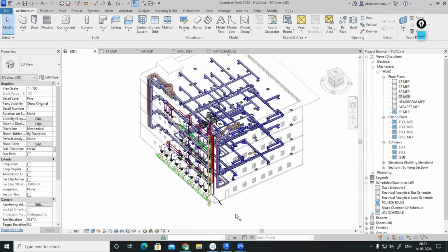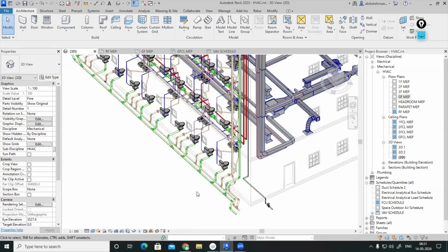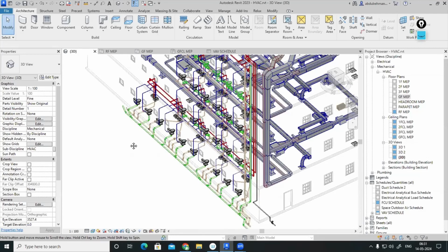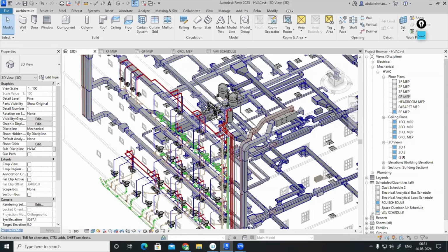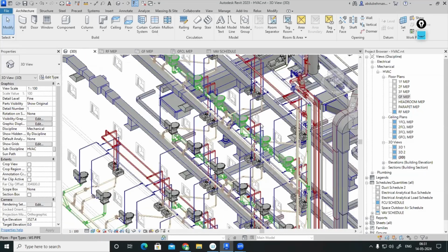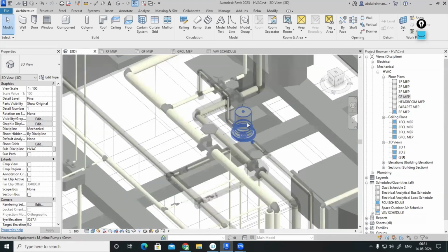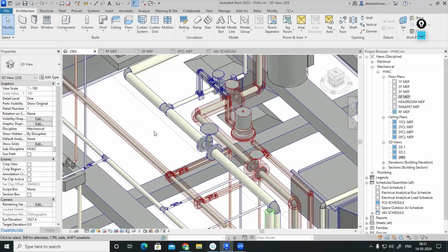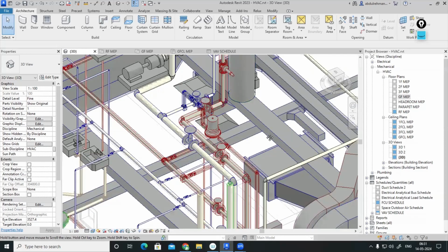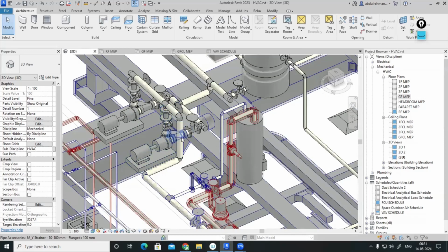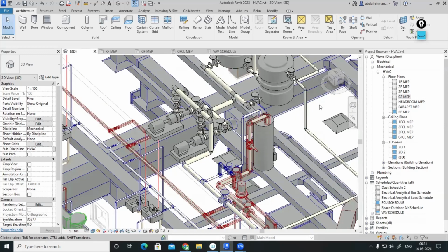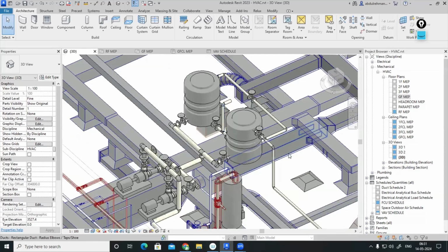In our projects, we did plumbing: soil line, waste line, correct. Then cold water supply. Then hot water supply has completed. Then hot water recirculation has completed. Centralized water heater we have placed. Booster pump connection, the hookup. This valve connection is called a hookup. Hookup has completed. Then inlet line, bypass, overflow, that has been done.